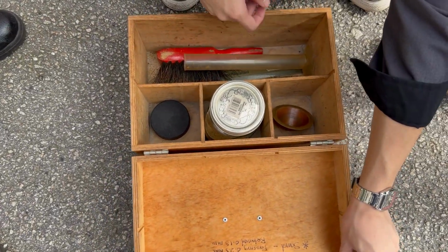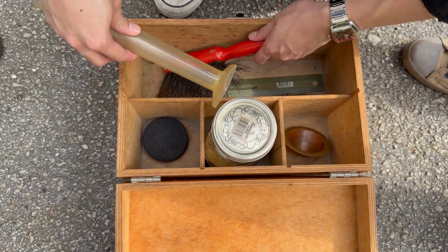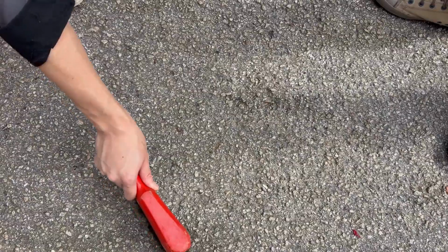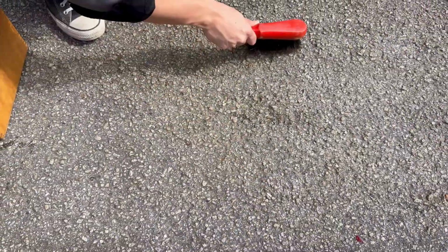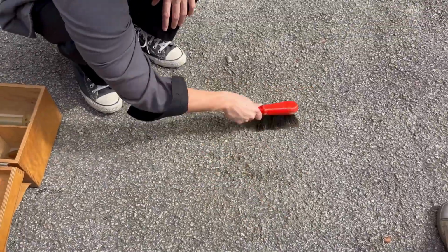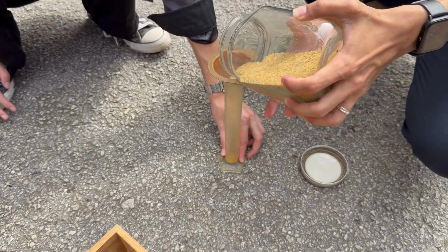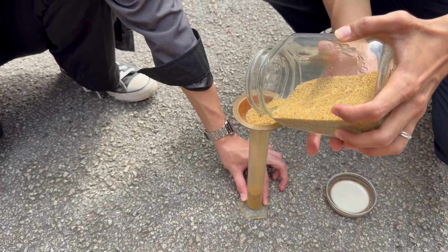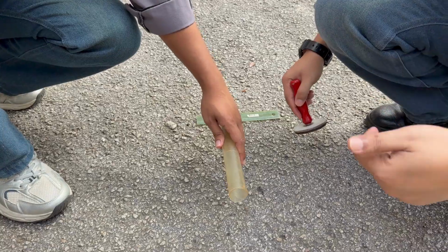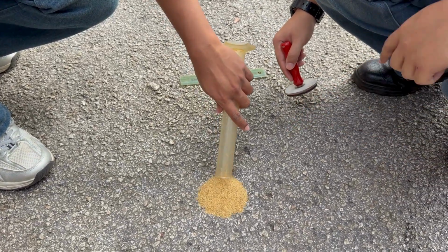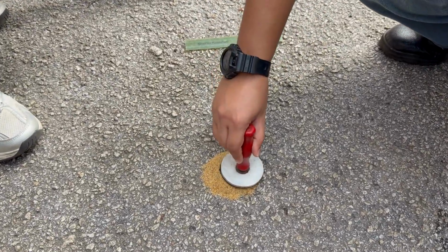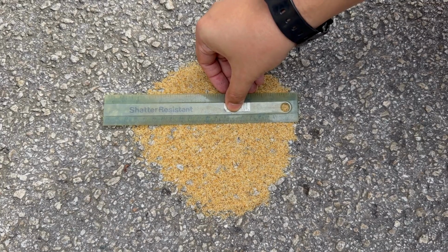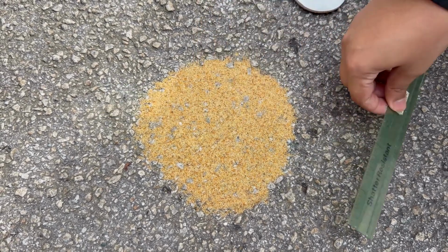For the sand patch test, the apparatus is a brush, measuring cylinder, rubber disc spreader, and ruler. Before conducting the sand patch test, the test surface is first brushed thoroughly to remove loose particles, dust, and debris. Next, the amount of sand that will be used in the testing is measured by using the measuring cylinder included in the sand patch kit. Next, pour the 10 ml volume of sand onto the surface and spread the sand evenly in a circular motion. Finally, calculate the sand circle diameter and record the data.